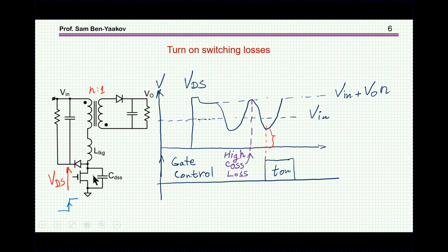That is, we'd like to move the energy that goes into the capacitor back somewhere as losslessly as possible, that is, without losses if possible, or with reduced losses. Aside from this major objective, we have another objective here, and that would be to achieve zero voltage switching of this main switch.